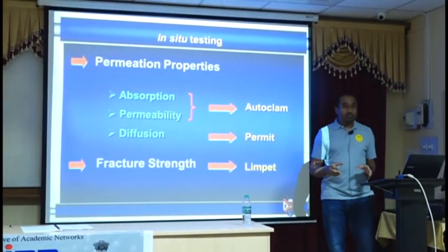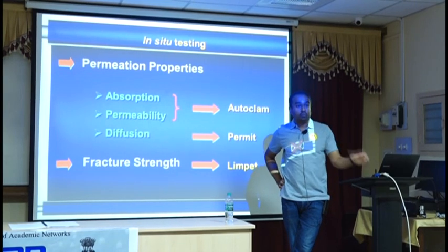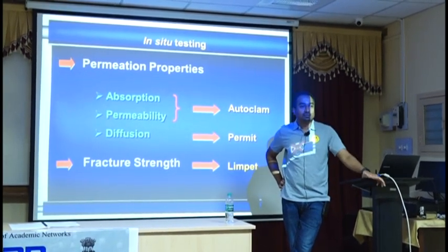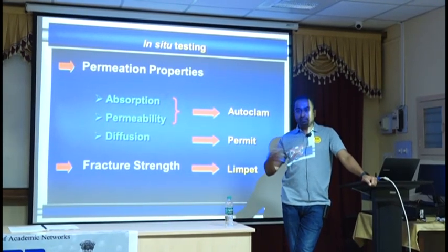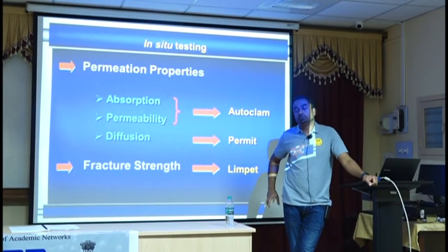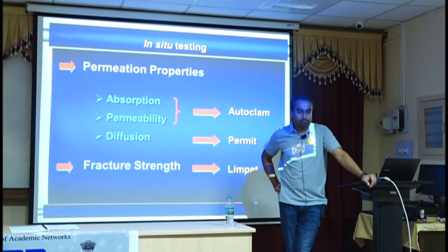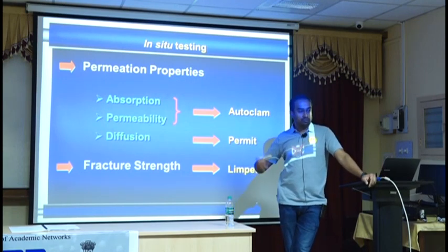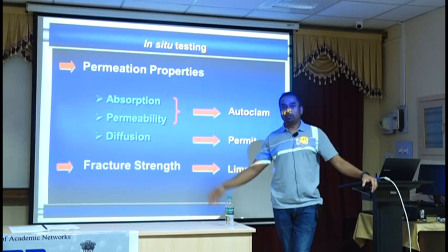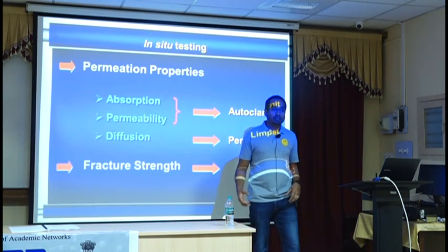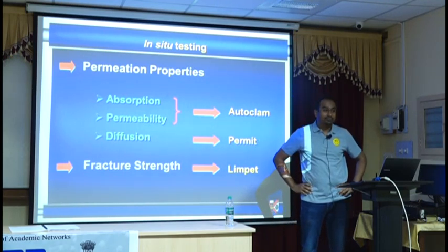Does a wet material absorb anything? A wet material, completely wet material. It's unlikely. By that stage, it'll be more diffusion rather than absorption. So the prerequisite is the concrete should be dry. So you take a concrete, you dry it, and you put it into a moist environment or water environment, and then you measure the weight change. Right? That's it.